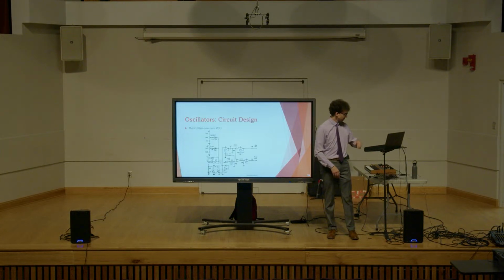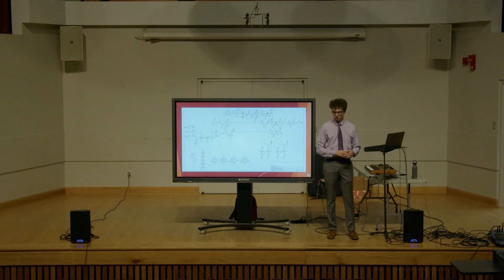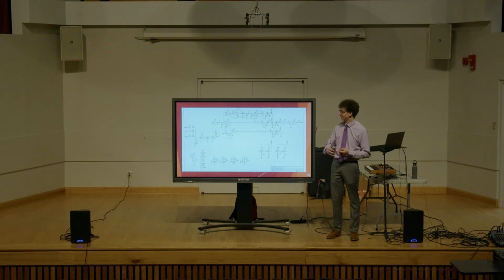So the basis for my oscillator is Moritz Klein, here he is, his oscillator design. And it's a sawtooth core oscillator, which you can then take to manipulate into other shapes. The frequency for this is voltage controlled, but the pulse width, for example, on this design is analog, so it's a knob, which I had to work around a little bit. My design for this is a little bit more complex, where I've also added a triangle source, and then I've implemented OTAs to mix between the signals so I can have the wave morphing function that I wanted.